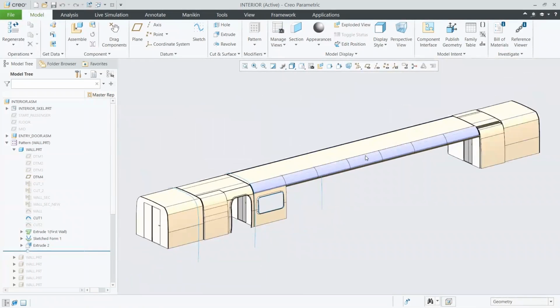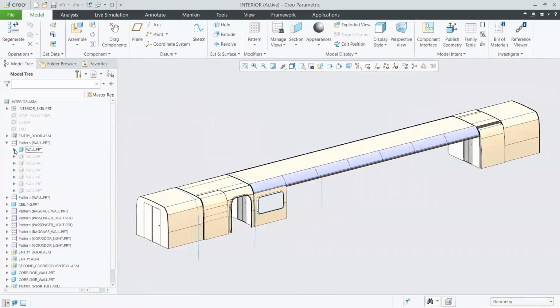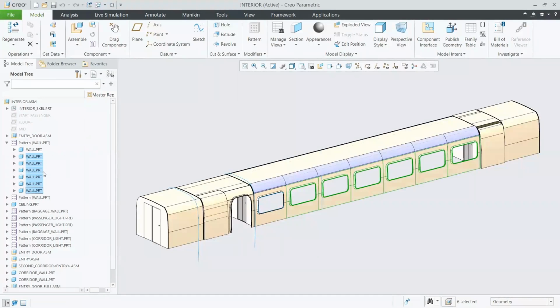And I don't have to have the whole train. If I'm just working on the interior, that's all I have to work on. I don't have to load up all of the other geometry, have this monstrosity that I'm working with and viewing all at the same time. And that's confusing because there's so much there. And also it really slows down the process. It takes time whenever you're working with these huge assemblies just to rotate around and let all of the geometry load. It's time consuming. So if you don't have to look at all that, don't just hide it. Just look at what you need to.